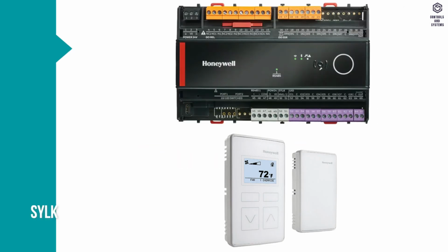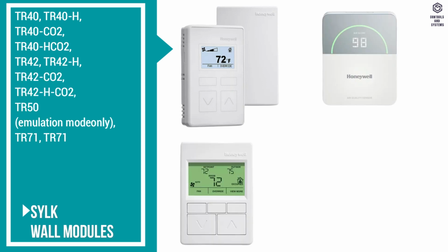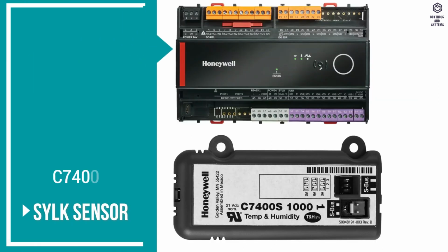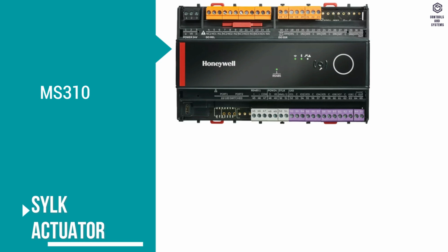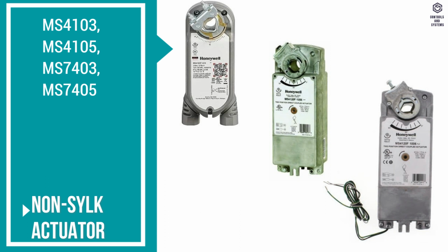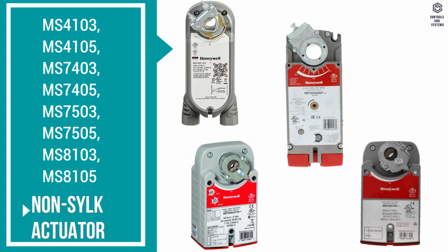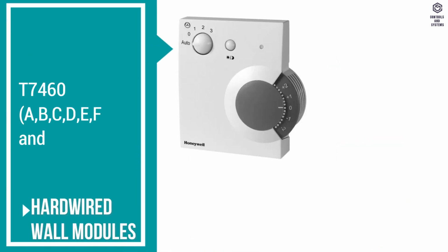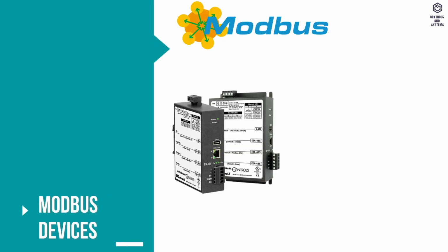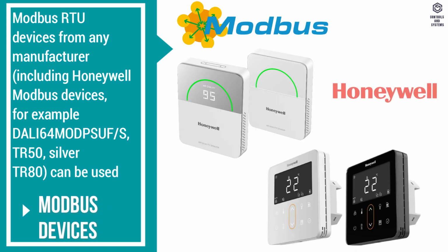Supported devices: SylkBus wall modules, TR40 series, TR50, TR71, TR75 and TR120; SylkBus sensor C7400S; SylkBus actuator MS31 series; non-SylkBus actuators, MS41 series, MS74, MS75 and MS81; hardwired wall modules, T7460 series and T7770. Modbus devices: Modbus RTU devices from any manufacturer can be used.